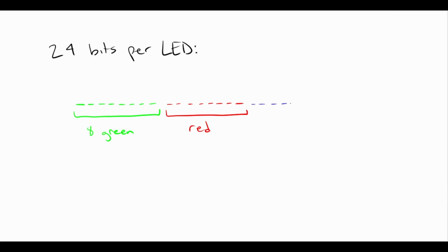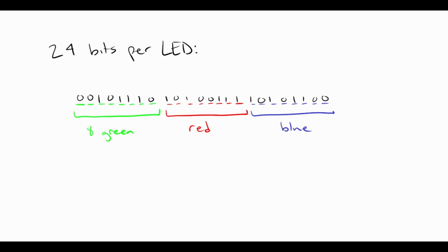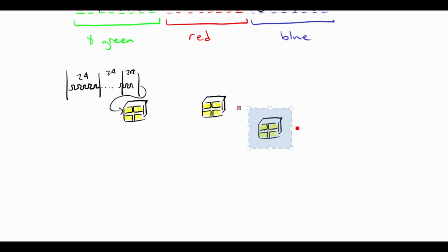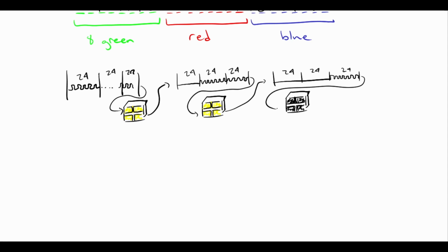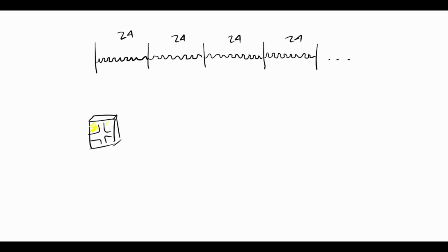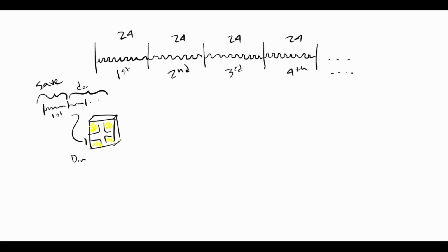So we've got this string of clock signals with the data encoded in them. What we need to do is send 24 bits of data representing the 8-bit values for the brightness of the green, red, and blue LEDs in the string, in that order. Each LED will block the signal from reaching the subsequent LEDs until it has had its fill of 24 bits. Basically, if we have 10 LEDs and each LED requires 24 bits, we'll need to send a total of 240 bits. The first LED will receive the signal and will record the first 24 bits it sees, all while not forwarding anything out of its data output. So the second LED, and all the ones after that, will hear absolutely nothing of those first 24 bits.